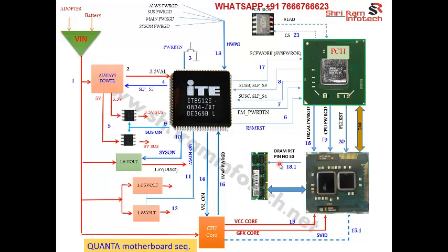You should get 1.5 volt if it's DDR3, and if it's DDR3L, here will be 1.35 volt. And if you find voltage here, that means the PCH sent DRAM power okay and the CPU is most probably okay, and you can omit the DRAM power reset check. After that, the CPU sends the next signal called CPU power good. Then the next signal is called PLT reset, platform reset.